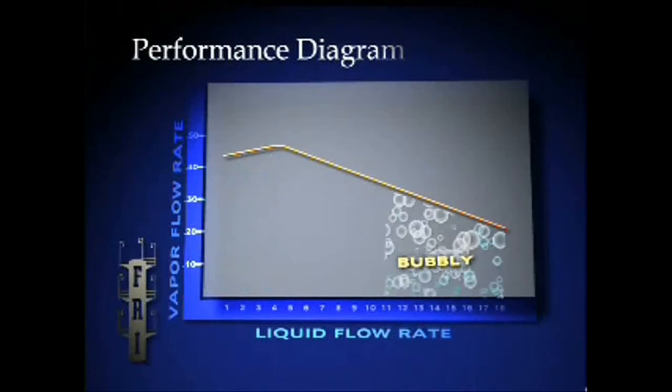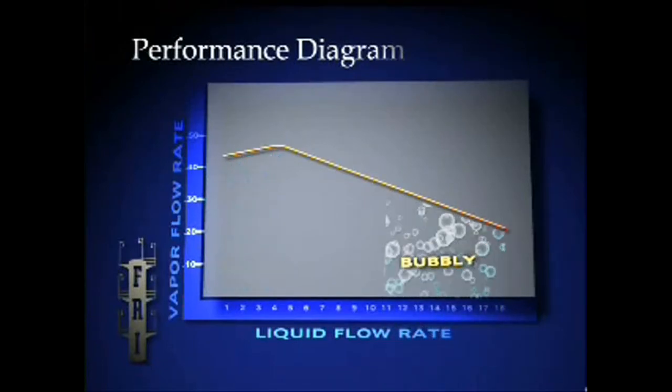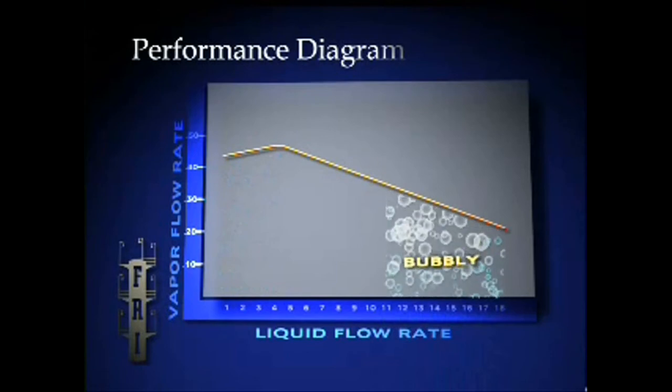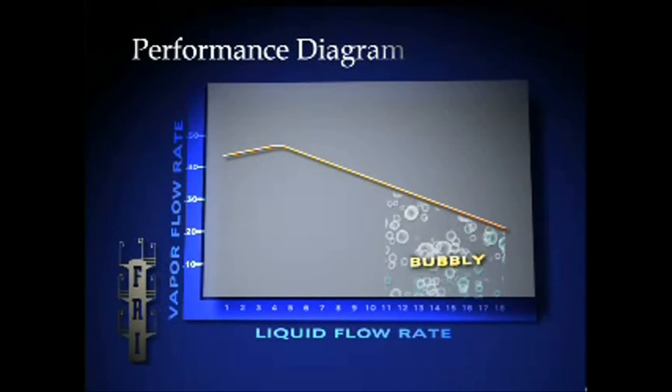The bubbly regime exists at the high liquid rate region. Here, the vapor liquid contacting is taking place under bubbly or frothy conditions. This appearance is typical of high pressure distillation.